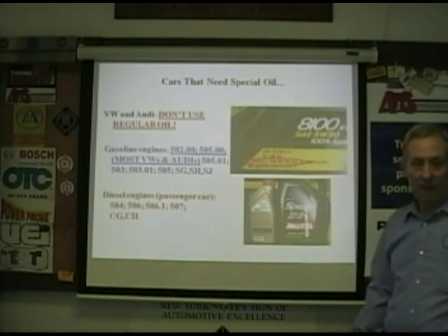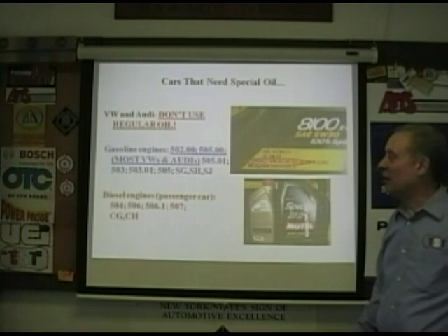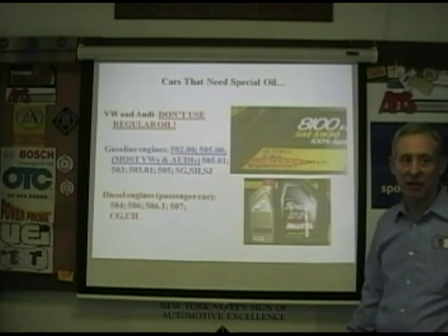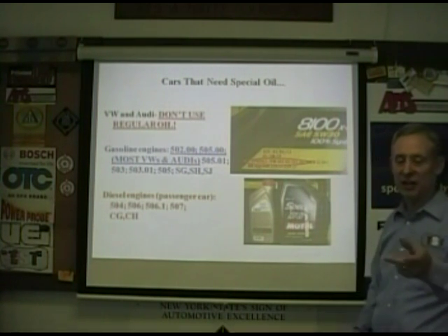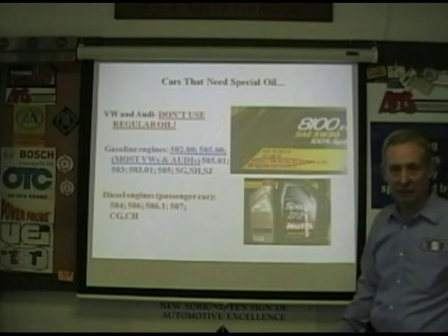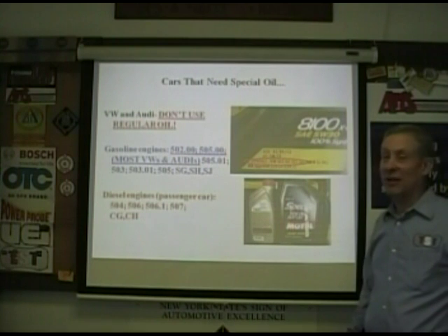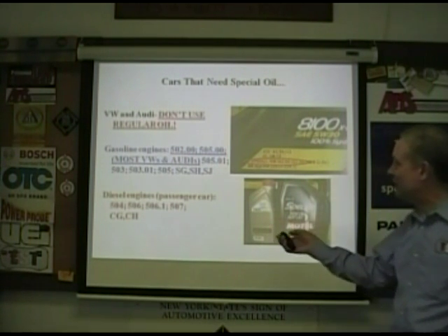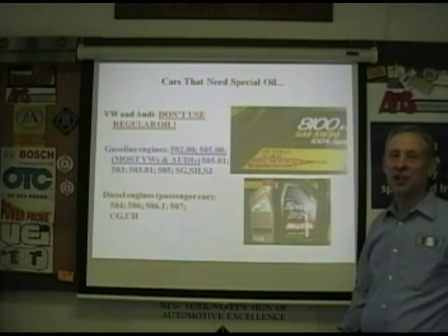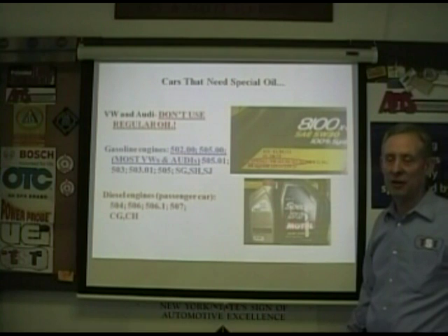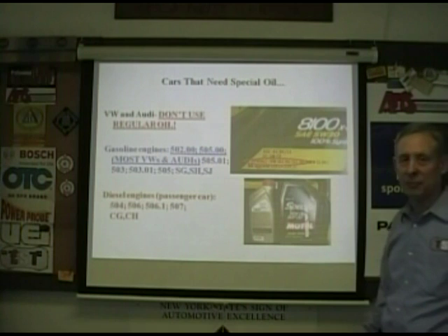And why is that? Because the friction modifiers in the oil are not up to the task of whatever those momentary loads are on those high load devices, cam lobes especially. And Vanos, because there are sliding gears that can bind. Does it have anything to do with sometimes the orifice and a thicker oil? That's a different problem. That's more viscosity related than additive rating related. But too thick an oil will block passageways that are purposely made small for quick pump up times. And as a result, you can get starvation, especially at very cold temperatures on cold starts.